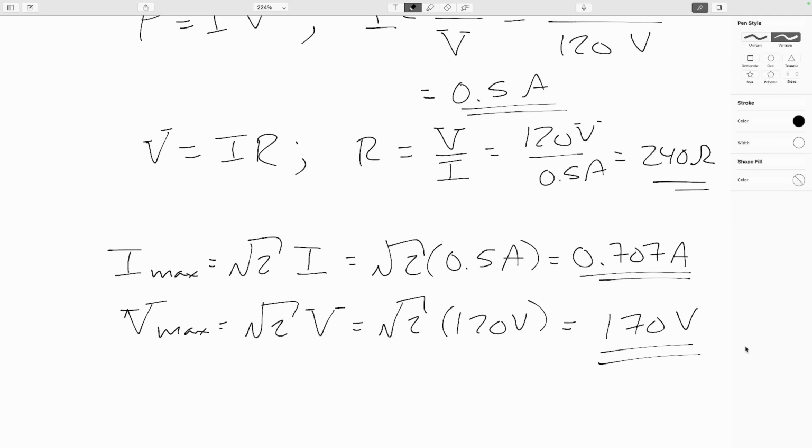So when you say that you have a 120 volt outlet, what that means is the voltage across the prongs in the outlet is actually oscillating back and forth between plus and minus 170 volts. So again, you can say that the average voltage is 0, and you definitely don't want to put your tongue across the outlet thinking that you won't get shocked, right? So you're more interested in, on average, how far away are you from 0? And it turns out that that's 120 volts. But to do that, you could swing out as far as plus and minus 170 volts while it's oscillating.